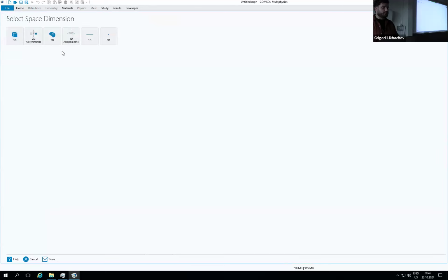All right, Model Wizard. As I said, we need to do a 3D simulation. You also saw it. And maybe this is the first time you do a 3D simulation in COMSOL. It's a nightmare, in that the simulations will take much longer than the 2D waveguides that you have seen. So we'll try to find a trade-off of the mesh that we use such that for today, it won't be the most accurate, but we won't spend the day waiting for this.